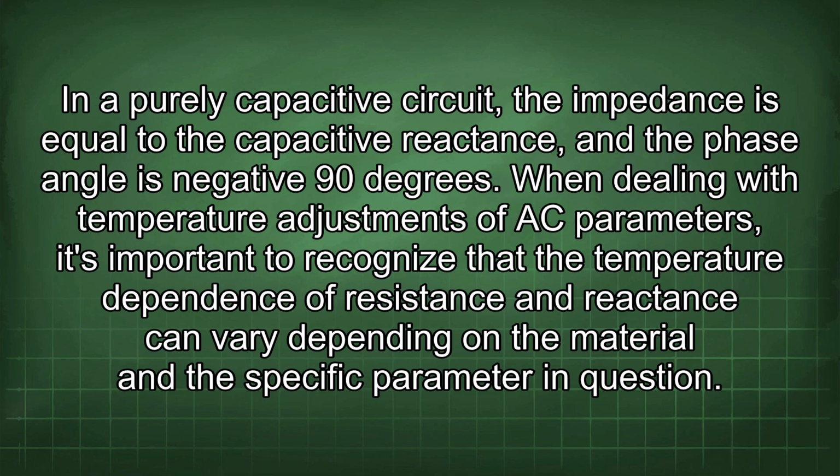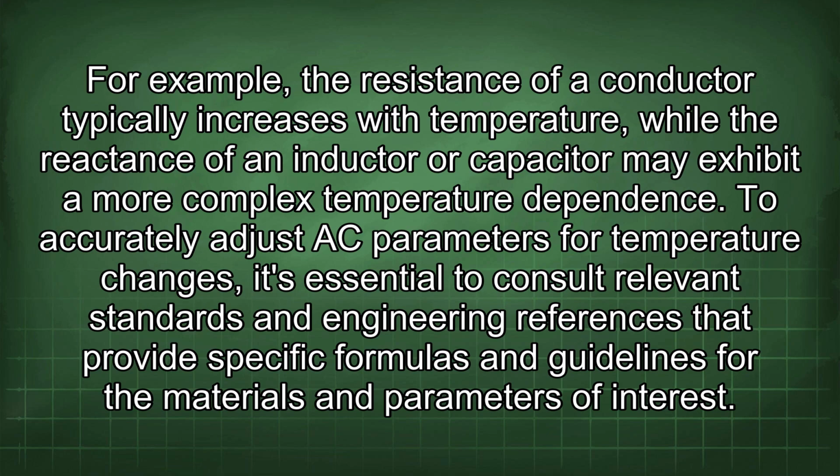When dealing with temperature adjustments of AC parameters, it's important to recognize that the temperature dependence of resistance and reactance can vary depending on the material and the specific parameter in question. For example, the resistance of a conductor typically increases with temperature, while the reactance of an inductor or capacitor may exhibit a more complex temperature dependence. To accurately adjust AC parameters for temperature changes, it's essential to consult relevant standards and engineering references that provide specific formulas and guidelines for the materials and parameters of interest.